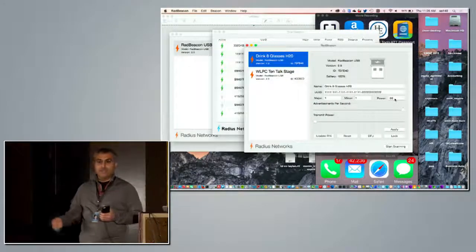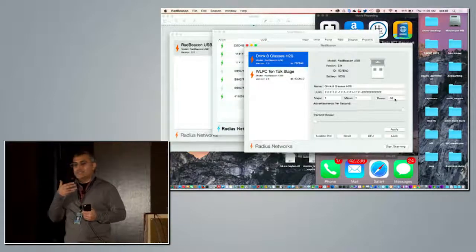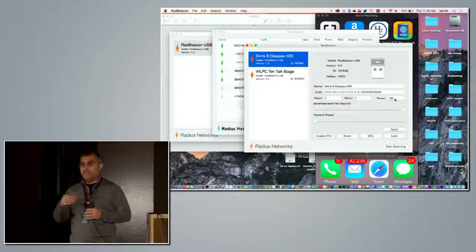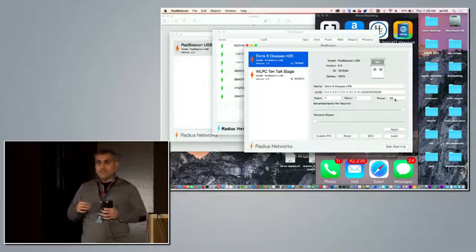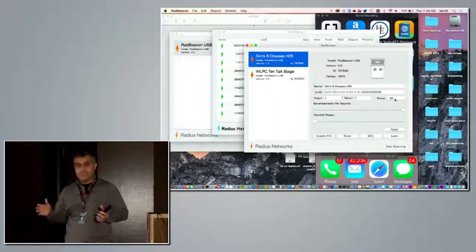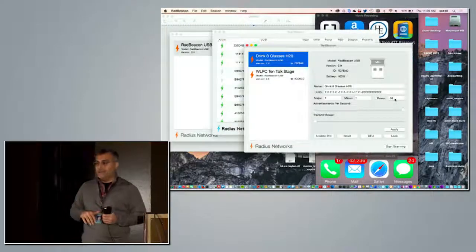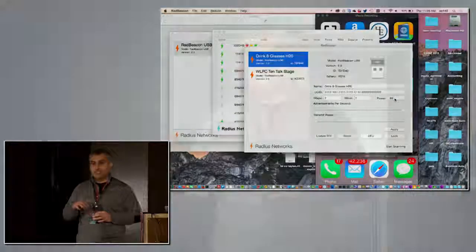application or the phone. So knowing the received power, the RSSI, and the reference transmitted power 1 meter away from the iBeacon, it does a path loss calculation in iOS, and it does some magic loss factor calculation to determine how far you are from the beacon. So we'll do a quick test to see if this really works.